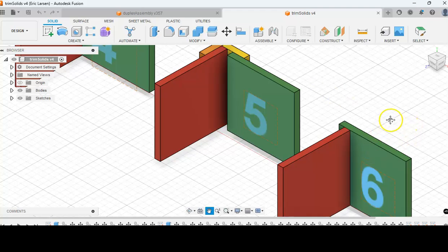Your construction leaders will tell you what they think. Now 6 is an example of a bad corner. You can't put trim on a corner that is like this. What you have to do is rip this edge off. Get yourself a Sawzall and just rip it off, and then you can put your trim on. In the process of cutting it away, you might make a sort of ugly looking corner, but that's fine.